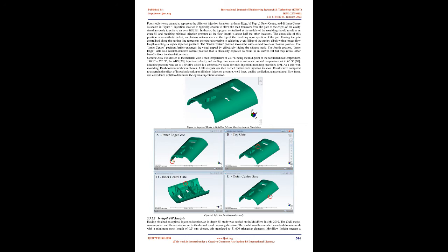27 experiments were carried out according to the design of experiment, DOE, and results obtained indicated that melt temperature was the most significant parameter affecting warpage. The study resulted in recommended settings for all parameters of interest.